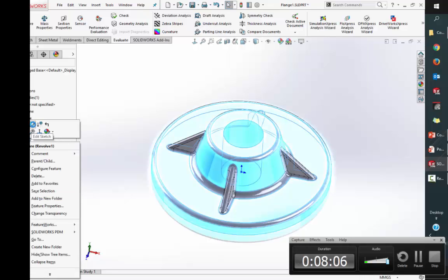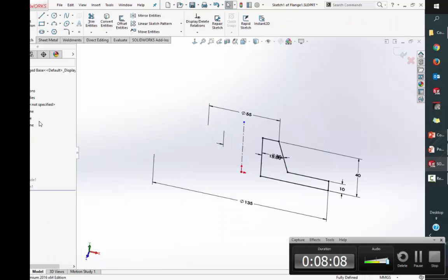So one of the issues you run into quite frequently is that in the sketch for the revolve that I have going on, you'll see that I have this spacing between the center line and the inside of my shape there. Well, when you revolve that, it creates a hole. The downside I have here, where I went to the other holes and was able to right click and suppress those items out, is that with suppression I'm basically telling SOLIDWORKS, don't do this feature, all right? Those holes were cut in on their own, and so when I suppress them, they all disappear.